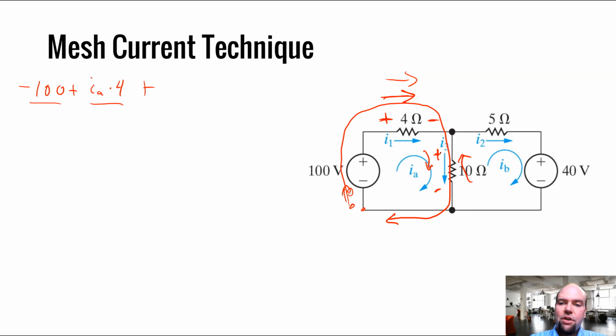Well, like I just said, if I'm looking for the voltage oriented like this, and I'd like to use the equation V equals IR, then I want an expression for the current flowing down in this direction. IA was flowing down in this direction, and IB was flowing the other way. So IB is labeled flowing up, and IA is labeled flowing down, and I want the expression for the current flowing down so that I can use the equation V equals IR here.